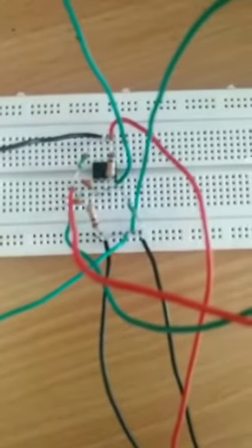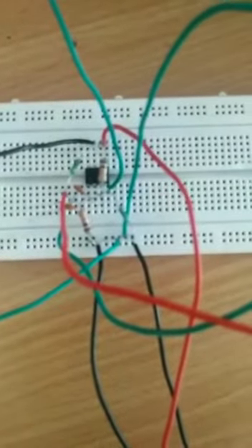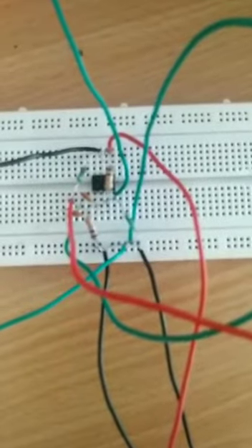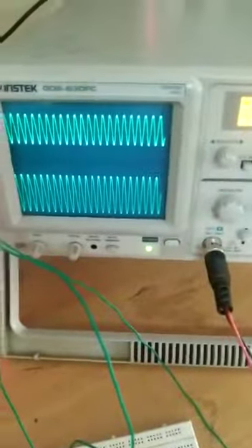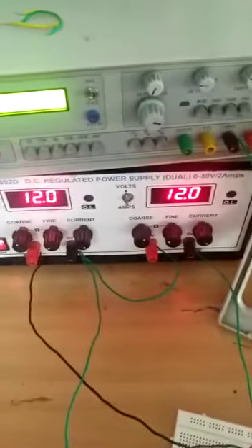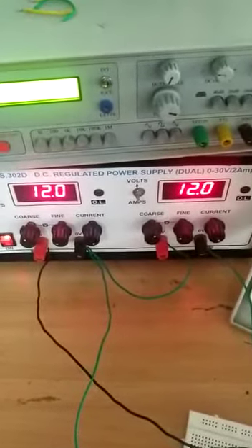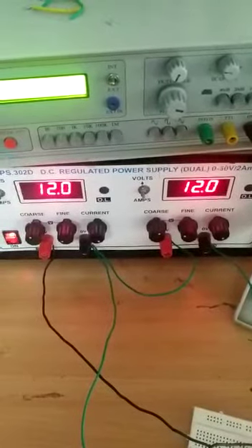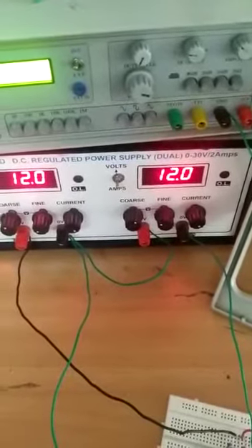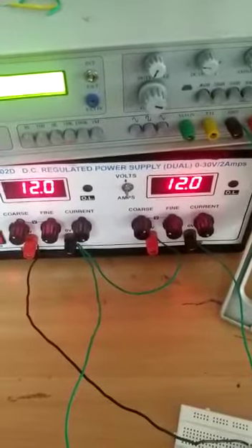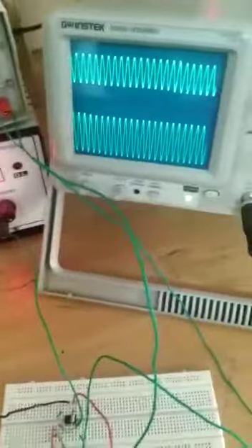For this circuit diagram, I have done the experiment connections here. See, I used the op amp, two 2 kilo ohm resistors, two 10 kilo ohm resistors and two 0.1 microfarad capacitors. The input I have given from the signal generator, and we are measuring the output as well as the input in the CRO, and we have used the DC power supply. For pin number 7 I have given plus 12 volts and for pin number 4 I have given minus 12 volts. By varying the input frequency, we will measure the output voltage in the CRO.